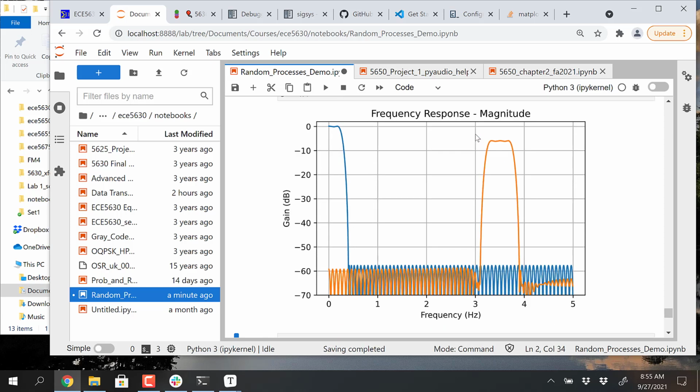There's the filter. The amplitude is reduced because I've shifted it to positive and negative. I'm only looking at half the plot of it now. So according to the way the synthesis works, though, I'd have to synthesize that with an amplitude of 2. So I'd have to do some scaling in here.